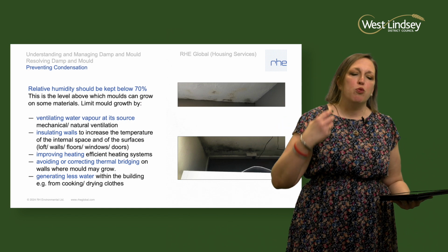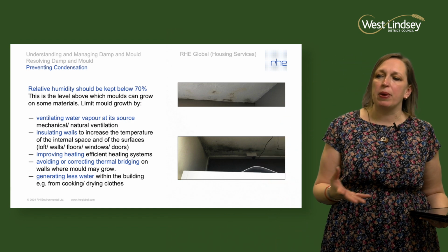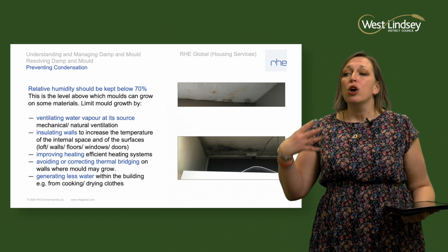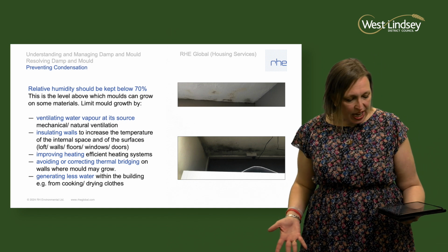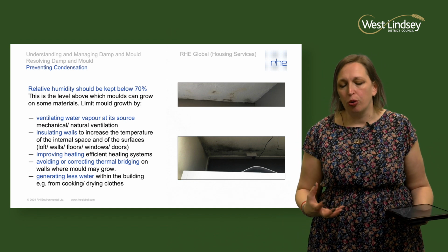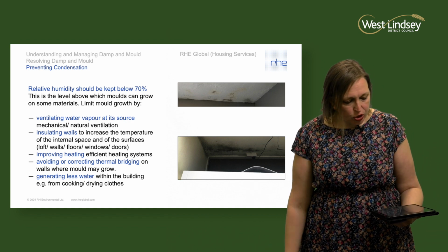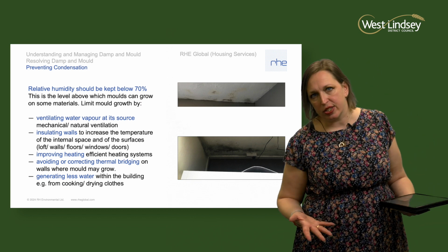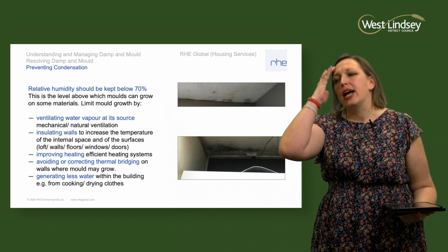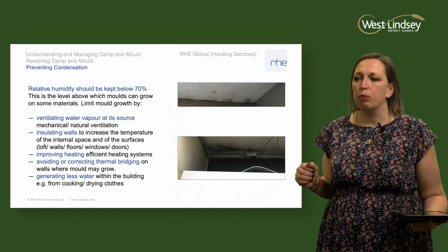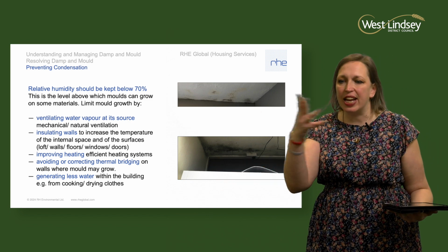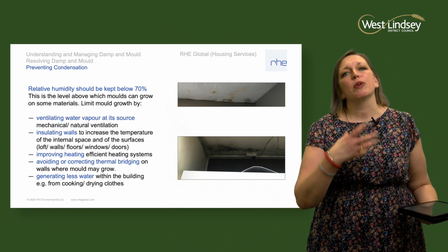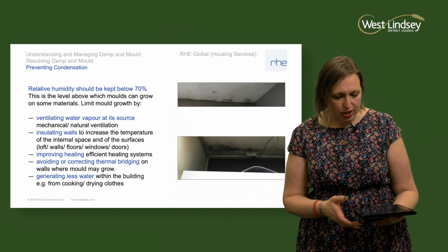We can talk to people reasonably, but we can't expect people to not bathe, to not wash their clothes and to not cook meals. Those are reasonable activities to undertake. You know, it is a house, it's not an ornament. We need to live in it. So we can talk to people about, for example, making sure that you've got the extractor fan running when you're bathing and make sure that the door's closed so our moisture-laden air isn't going throughout the house, it's staying in the bathroom and being extracted. But we can't say to people, take fewer showers. You know, it's all about what's a reasonable approach within that dwelling.